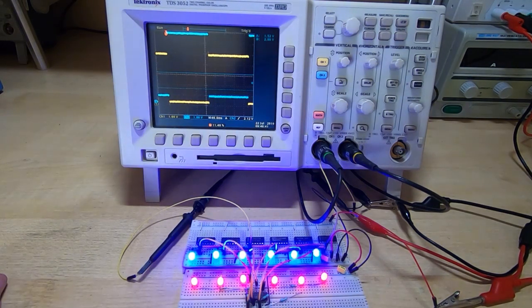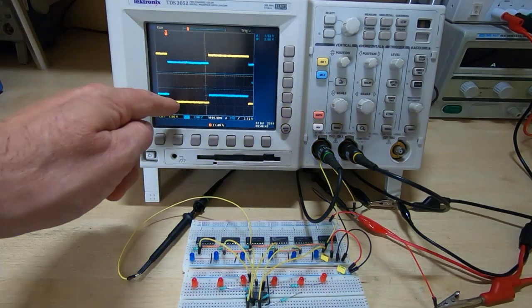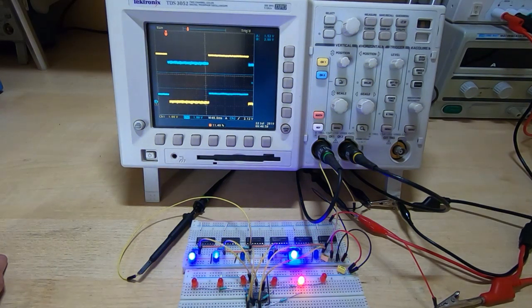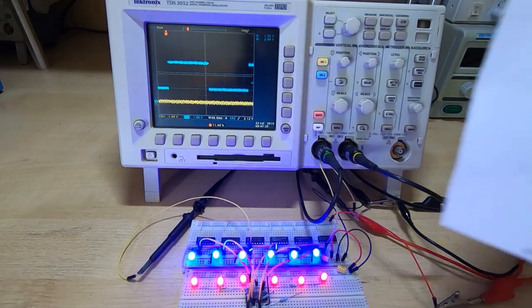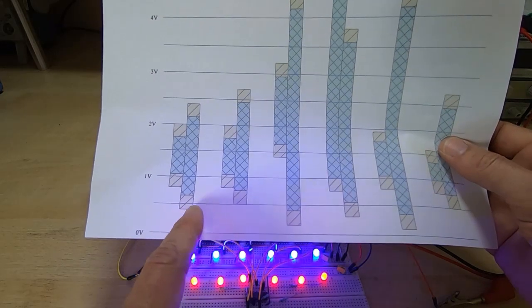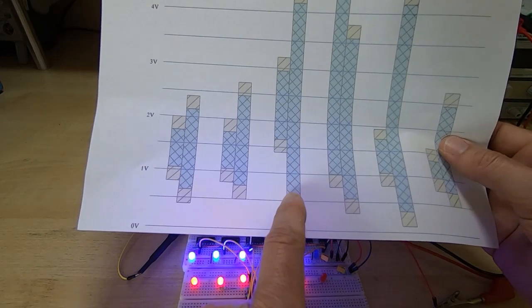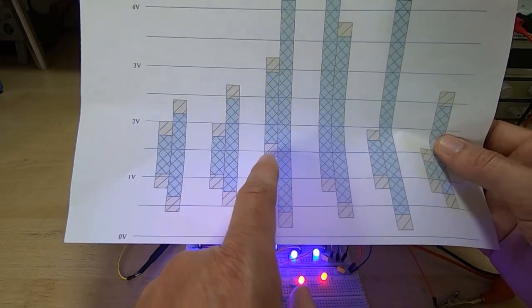So I'll change this now. I'll set that to 2 volts high. You can see that channel 2 is actually showing the input value, and now I'll go to the low level and I'll change that to 0.8 volts, and straight away you can see that we have an issue. You can kind of see what's going on here if you look at the input values compared to the output values, and in particular why the HC version is still working. You can see this is the effective threshold for switching.